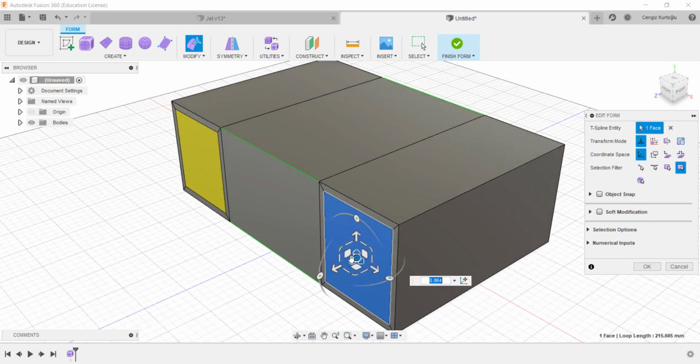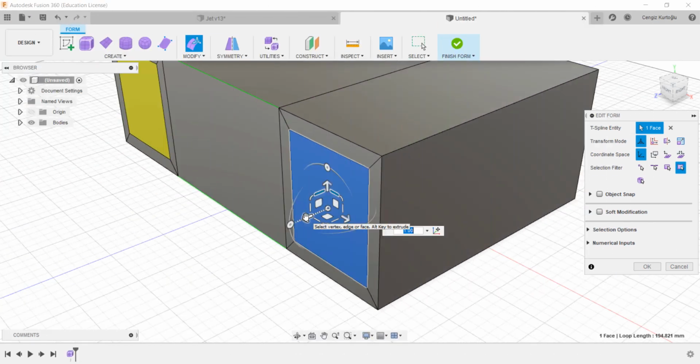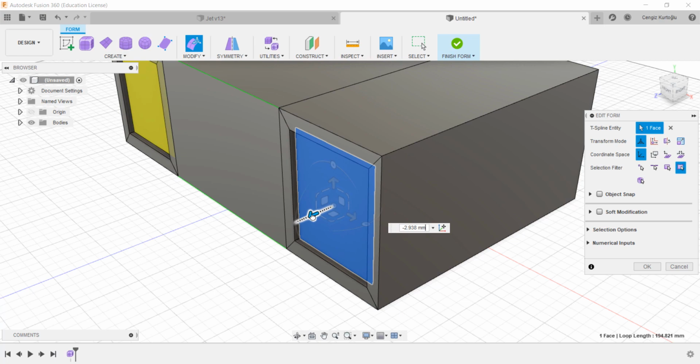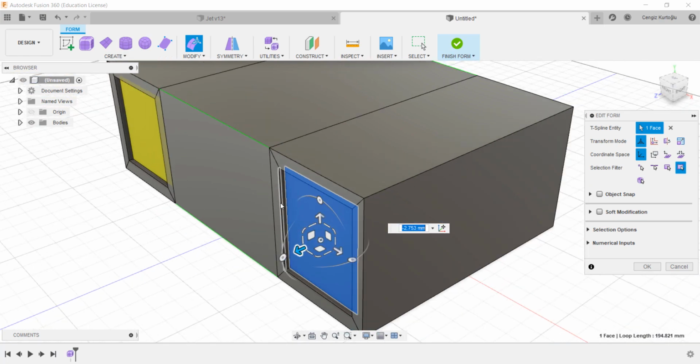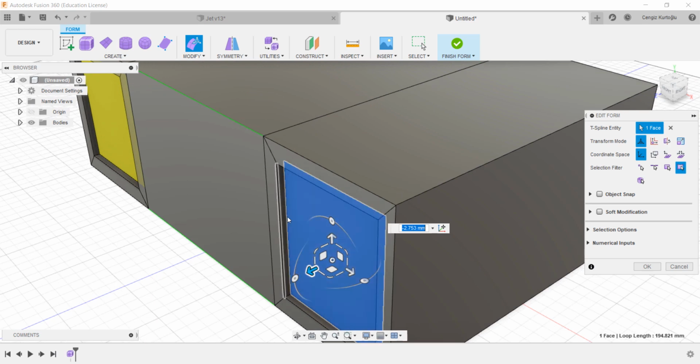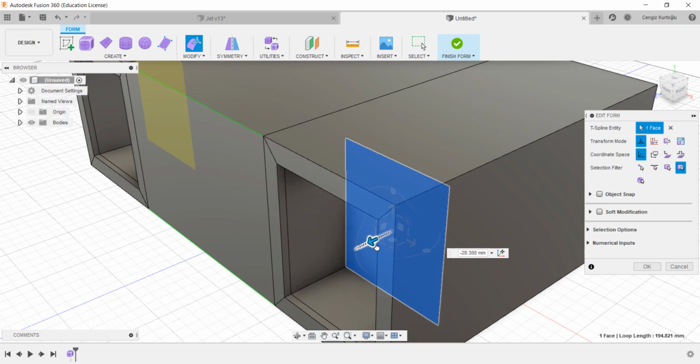To create a depth of the inner part, we have to move the arrow in the z-axis inside, just a little bit, while pressing and holding Alt key, because I like to create a sharp transition in the edge of motor parts. And then we can again move the arrow and push it inside, as you know, holding Alt key to create new faces.